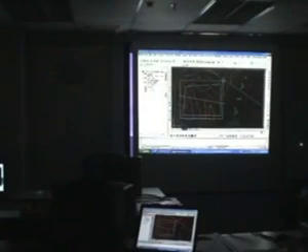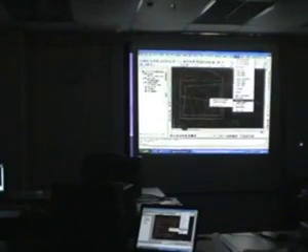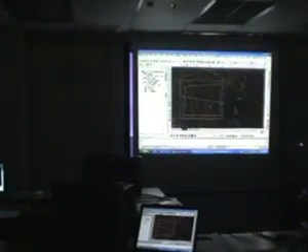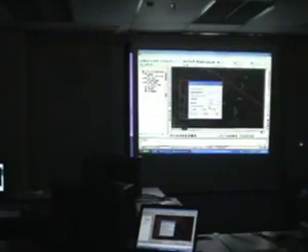Now we've defined our original and our proposed level, and we've defined our site. To run the calculations for grid, it's very easy. You just need to pick calculate total site volume and select the site. Here is where you can apply any volume correction factors if you need to. In an actual project, usually for fill factors, you must put a little bit higher.